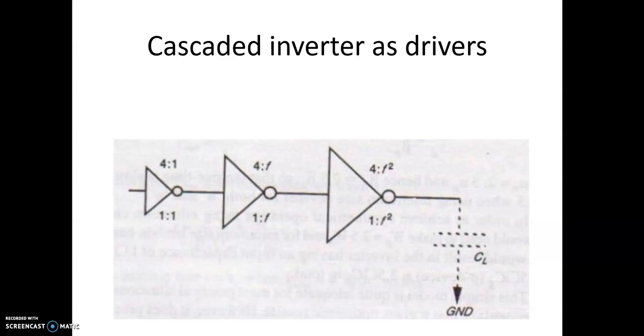If we have to reduce the resistance, we either decrease the length or increase the width. We cannot decrease the length beyond a certain value, so the next option would be to increase the width. But as we increase the width, the capacitance increases and the area occupied will also increase.